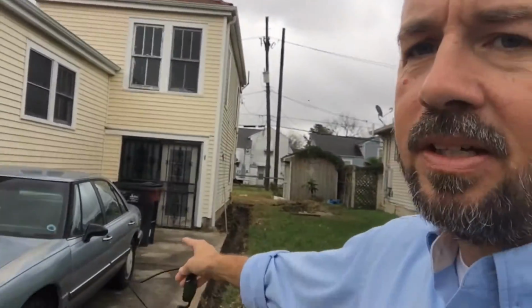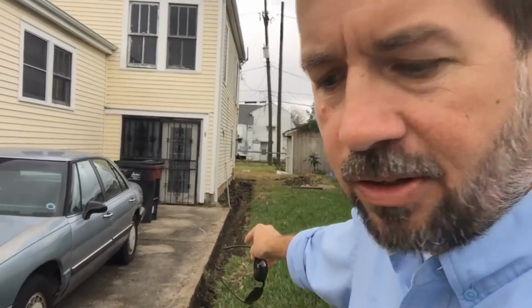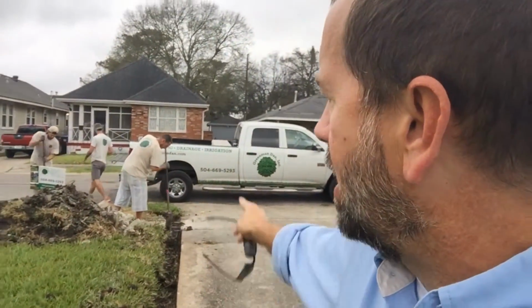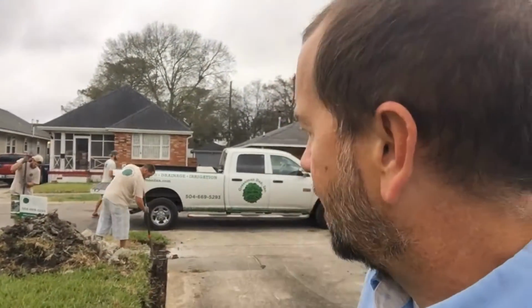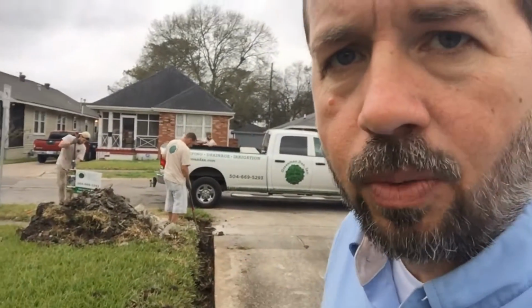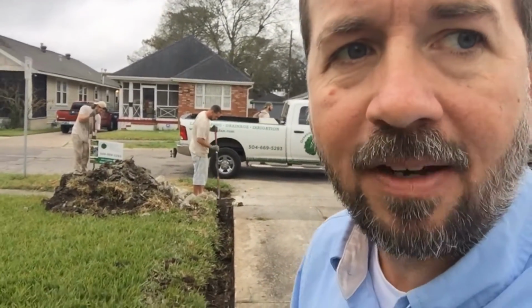So all that water that's pooling is now going to go into the French drain when it's full, and it's going to run out along the house and go out this direction to fill right into the rain garden right there, emptying in, and like I said, then roll out into the street. All of this trench is going to be filled with rock and a perforated pipe to let the water get in it fast enough.